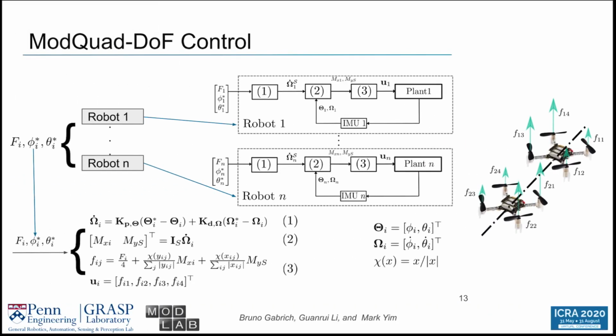The last step of the controller takes place locally inside each one of them, so at the firmware level. A PD controller is applied in order to obtain angular accelerations. The integral term is omitted since that could bring instability to the system as a whole. Given the angular accelerations, the forces for each motor are computed given the position of each module relative to the structure and also how many modules compose the structure. Therefore, with this approach, modules can cooperate, behaving as a flying conglomerate with improved yaw actuation that allows bigger structures to be formed.